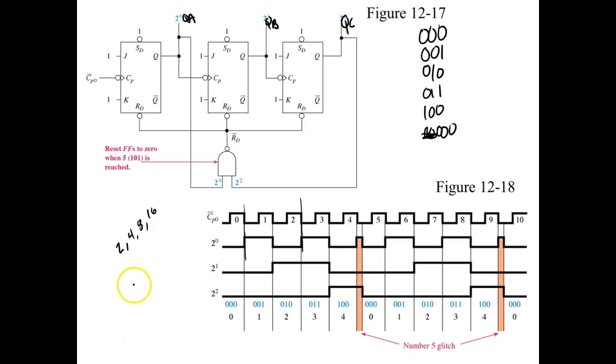So what we have is, I come over here, and the time it takes for one cycle is what we call the period. Now you notice on this guy, the amount of time it's sitting at a high and the amount of time it's sitting at a low is equal to each other. So we would say this guy right here has a 50% duty cycle. So the duty cycle is the percent of the period that the waveform is high.